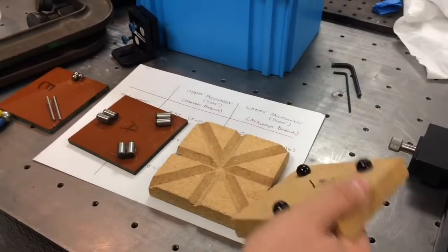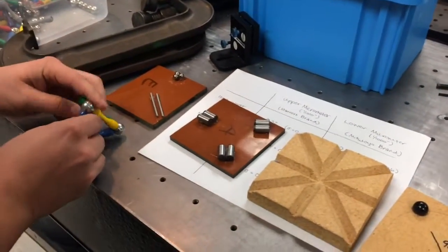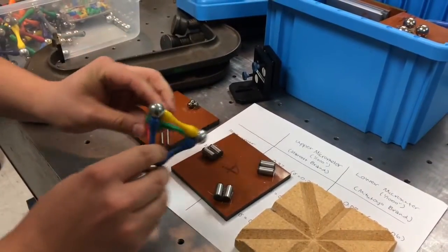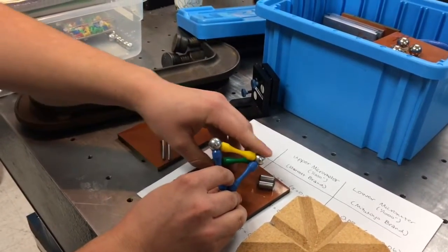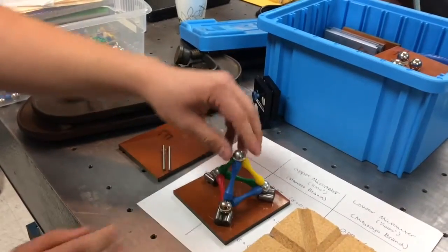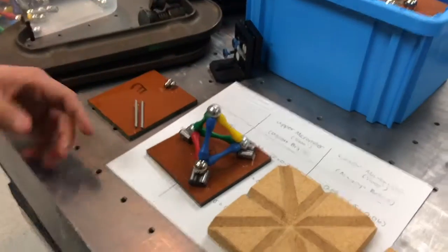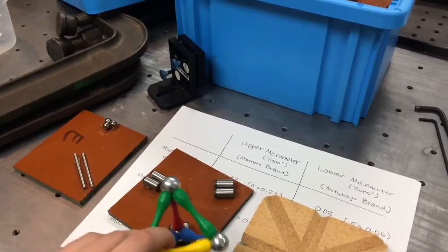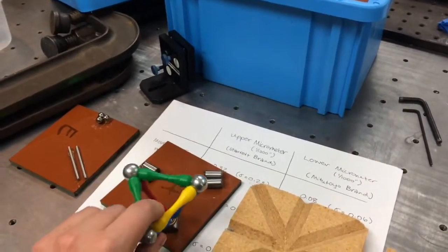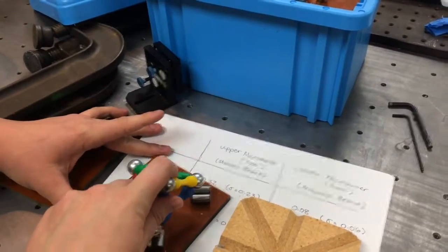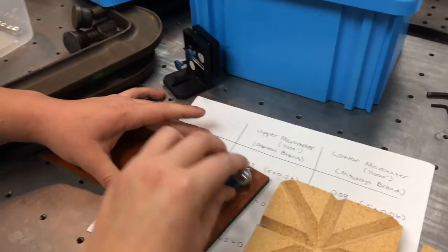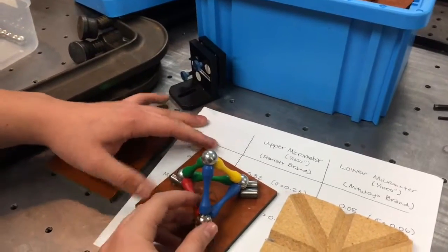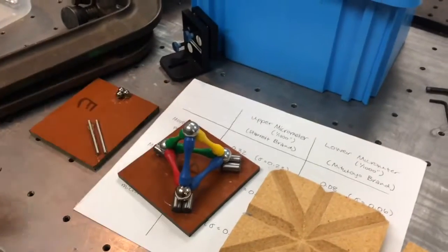You can actually see this again with this setup here. This is the 3-groove setup that I'm talking about, and if you pretend that this is some sort of optical mount, you can place the balls in the grooves, and you now have 6 points of contact, and this will no longer move. It's kinematically constrained. And you can see it's constrained because when you have this one, you can still rotate, but you're constrained from translating except in one direction. You add this additional constraint, and all you have left is 1 degree of freedom in this rotation, and then by having this final constraint, it is also constrained in that direction.